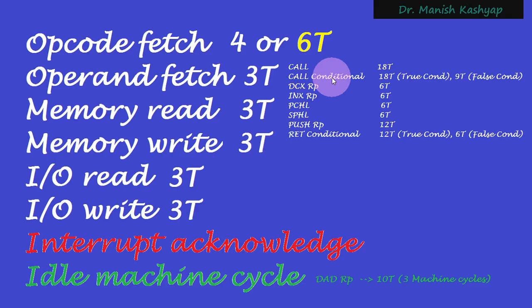We are already aware that whenever we make a function call, a procedure call, a subroutine call, or even an interrupt service routine call, the current contents of the program counter are kept onto the stack. So the stack is also accessed in that. Assuming that we are executing a CZ instruction, and the condition happens to be true, that is the zero flag is set, let us discuss what T states will be consumed.